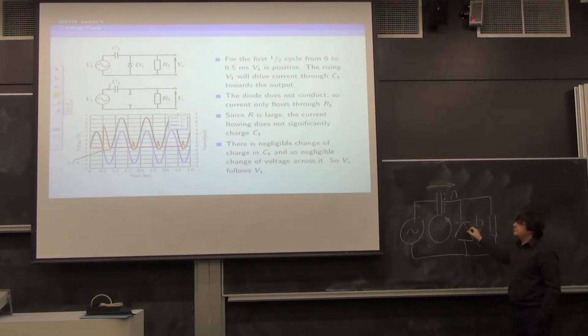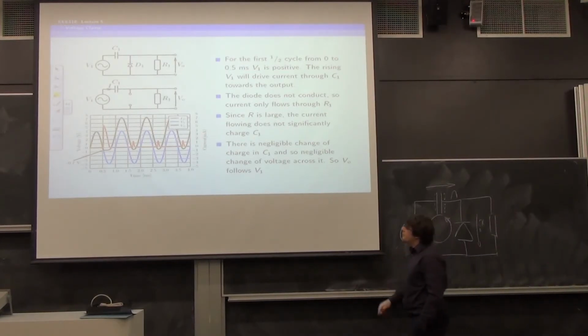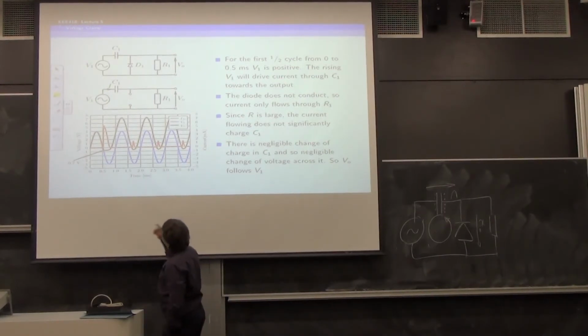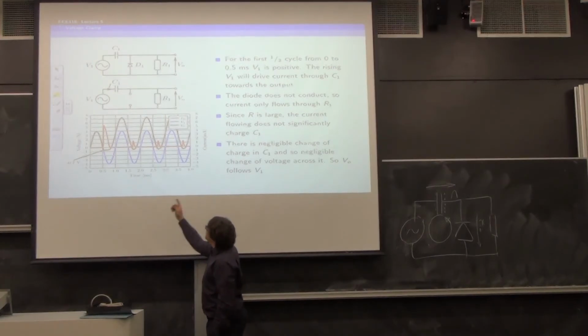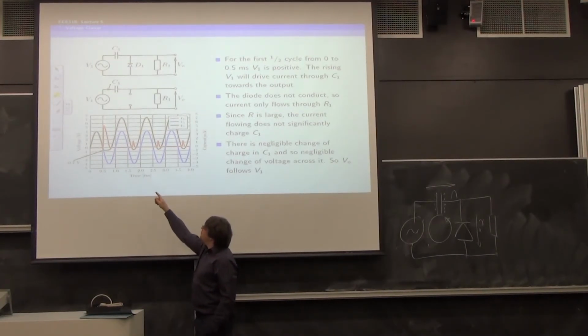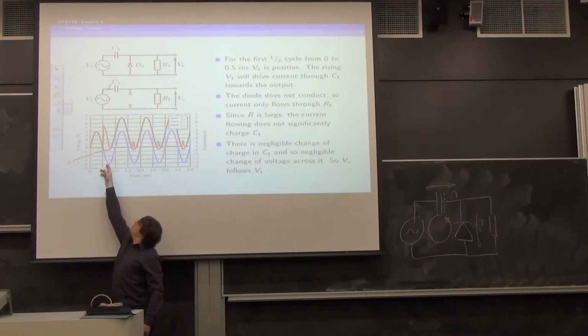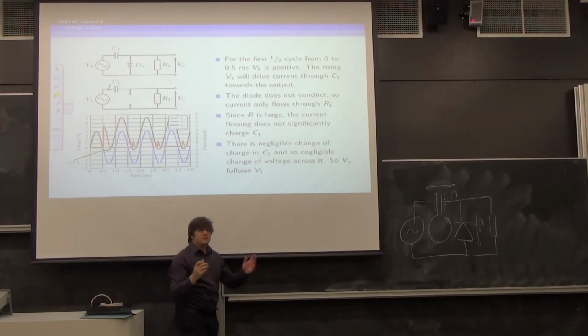So that's 0.7. So we are now in the region where we've charged up the capacitor, and if we could see capacitor voltage, which we can't, but if it was there, we'd see capacitor voltage has gone up by the difference between the bottom of the blue line and the bottom of the black line, which is just above. So the capacitor is now charged up.